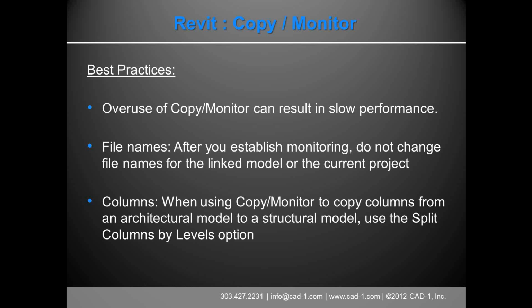So they won't work in yours. But the trick, kind of a workaround, is you can use this copy monitor process to change the objects from wall hosted or ceiling hosted to be face hosted. Revit won't let you change those in the families, but Revit will change it. So it can be kind of a workaround. I'm sure there's more information on that if that sounds like it's something useful for you.